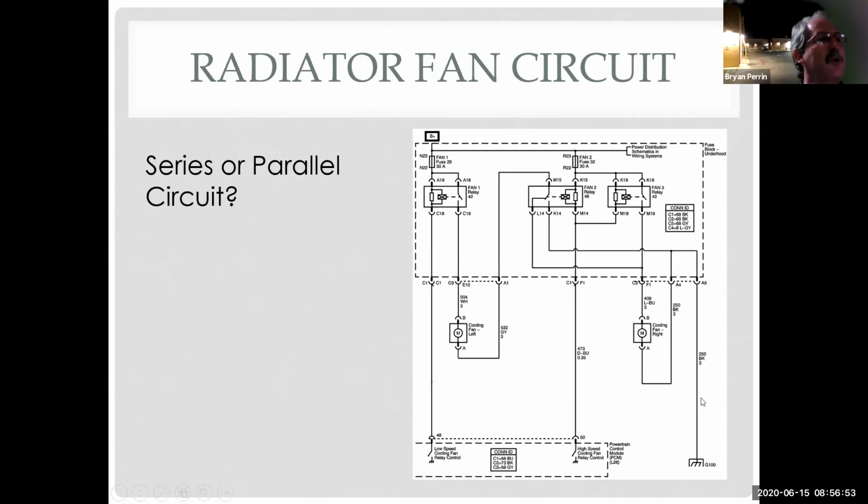So once we start controlling things by a computer, the next question we need to ask is, can I use the scan tool to control it? So if I'm working on an older car that doesn't have a computer, my first tool is going to be maybe a power probe or a DVOM. If I'm working on a modern car with a computer, my first tool is probably going to be a scan tool so I can talk to the computer. So depending on the year of the vehicle, I'm going to choose different tools.